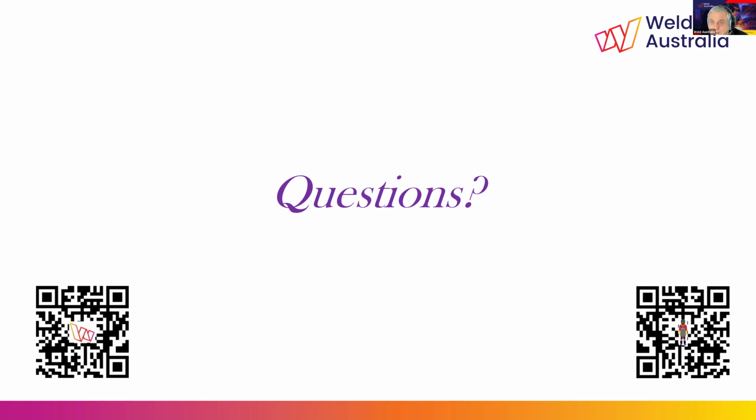Bruce? Yeah. Bruce, Kev Borner here. Regarding the comment I made earlier regarding the hardness problems in overseas materials, I have come to the conclusion that it's possible that I put a caveat in the welding procedures, particularly the WPSs as well, to inform the user that if you're using Australian material, the preheat tables that are included in there will be much the same as in alignment with 1554 series.